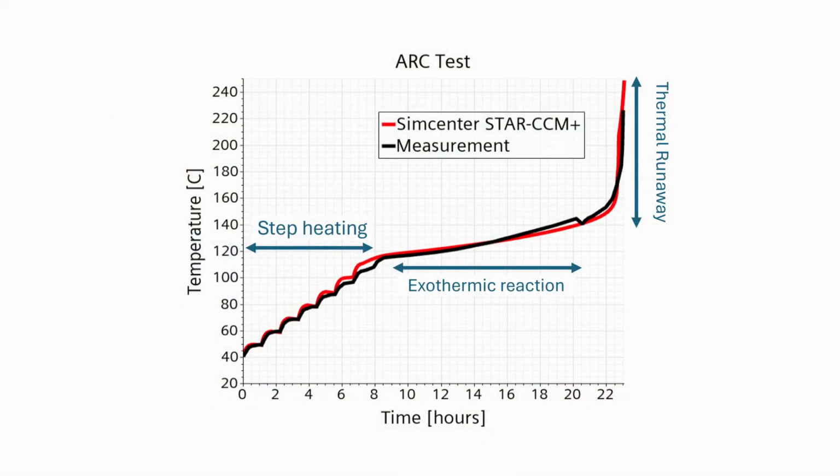So we simulate heating this battery up, and because we have this chemistry framework, we can now explicitly model all the reactions as they start to take off, and you can really track the behavior of the battery and the start of this thermal runaway event. And that's what you can see on the plot here. We've very nicely matched up the real experimental data and the simulation in SimCenter Star CCM+.